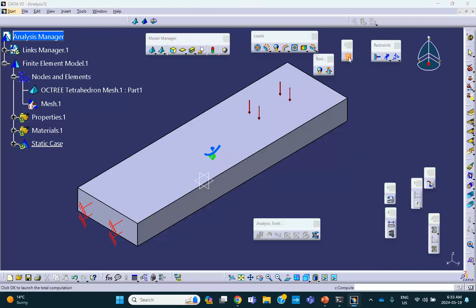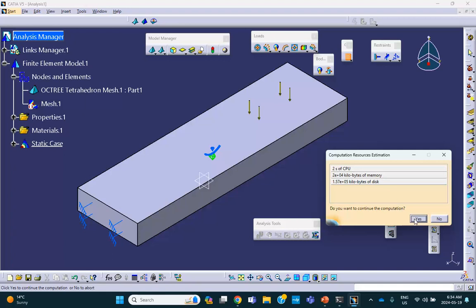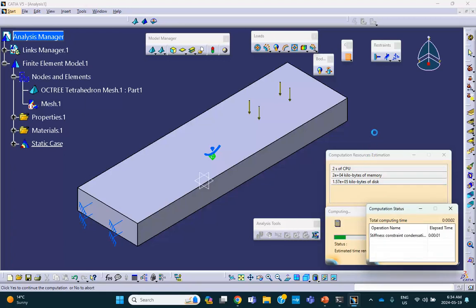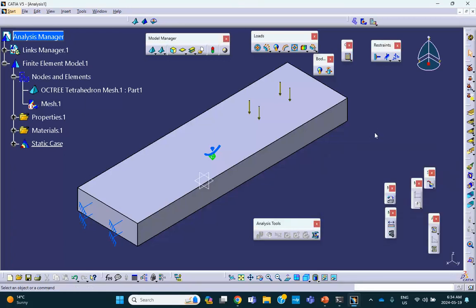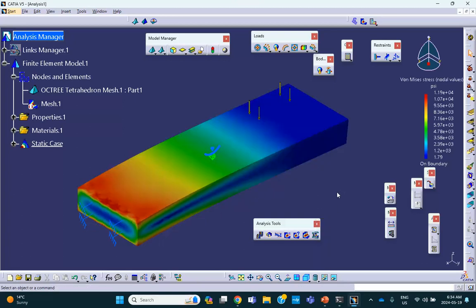That's really not the main thing here. So basically, I created my part. The place that I wanted to sew something, I sketched it, I filled it, F-I-L-L. I sewed it, make sure arrow is down, that box is unchecked, and then go to your analysis and mesh it. You see that it will respect that patch. And if you apply the load here, obviously it's going to go down. There we are. It pushed on that and it pushed it down.